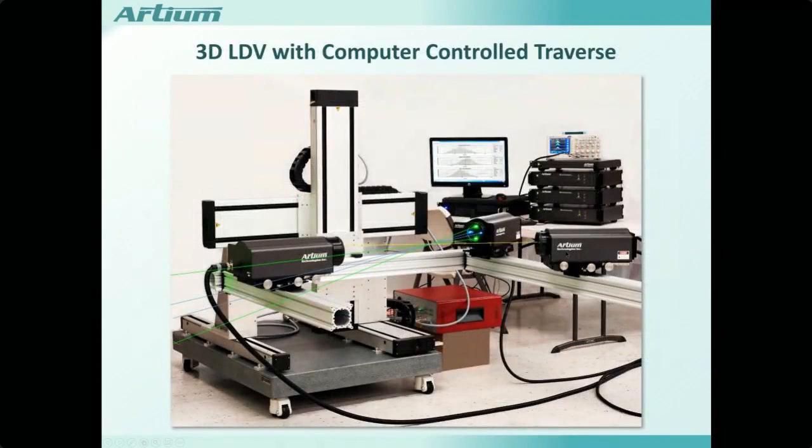We provide 3D LDV and phase Doppler systems. This 3D system consists of a 4-beam set, 2 green and 2 blue beams, transmitted from one transmitter, and the yellow beams from another transmitter set off at those plus or minus 30-degree angles that I described earlier. The receiver is set at the bisector. So we're getting good signal quality and equivalent signal quality from the beam pairs because we're sampling relatively near to the forward direction.